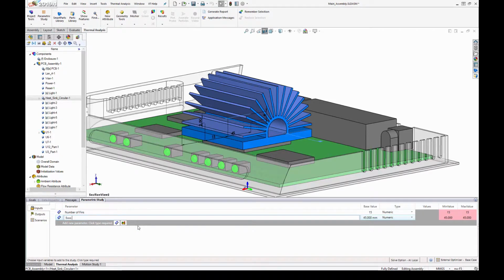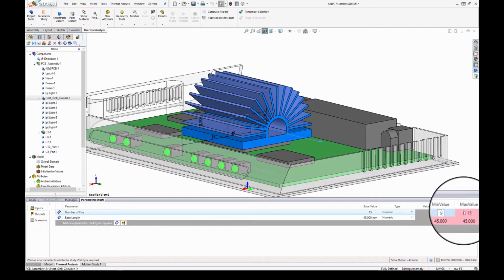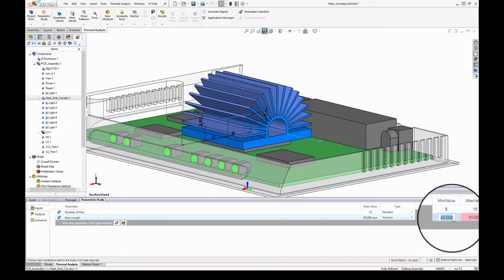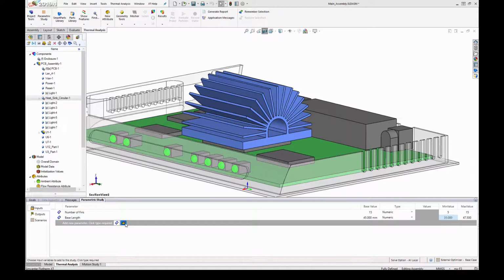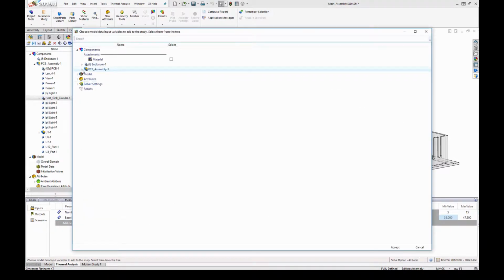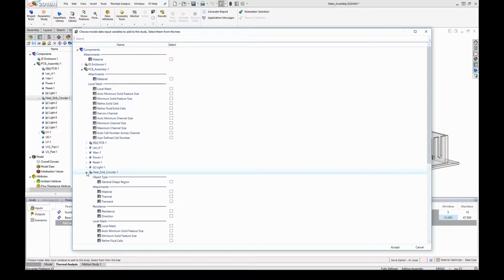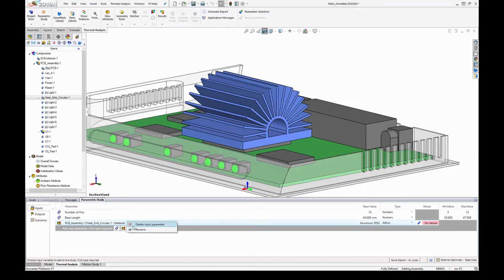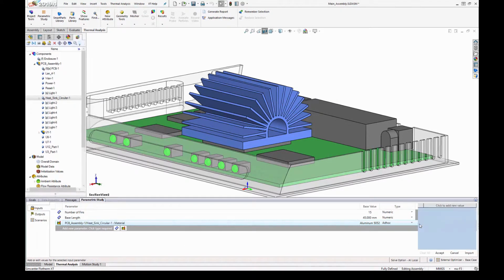Once the study has been activated, the user is able to set up the input and output variables for the study. For the input, you are not limited to numerical entries such as dimension, as a number of these external optimizers can accommodate input to say the material applied to a part. It is possible to define an ad hoc or linear step variation, as in a manual variation or a range as in DOE. Usually the output variables are left as just recording the value.